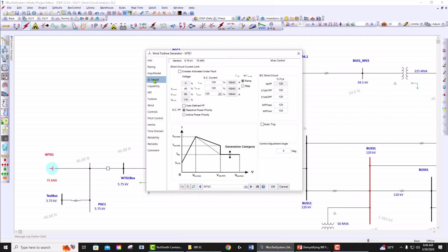The first thing I would like to cover is the current limiter, which is a voltage-dependent current limit, and then the power priority. In early generations of IBRs, there was typically voltage dependency: if IBRs faced a very close fault with a significant voltage drop, they tended to also drop the fault current. That means the IBR could not inject its full capacity or max current during the close fault. So they tended to reduce their fault current, while at higher voltages they could inject more.